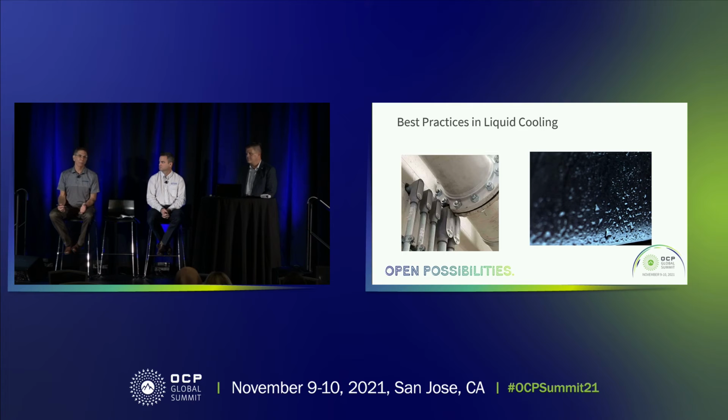Well, it happens to your pipes also, but you avoid that condensation moving from the pipe by putting insulation around it and keeping the pipe roughly at the same temperature as the fluid. But once the pipe temperature changes and certain climatic conditions come into the room, you're going to get moisture on there and it's going to collect. It's going to travel down the pipe like water and gravity want to do, and it's going to drip off and look like a leak, but it's not a leak at all.